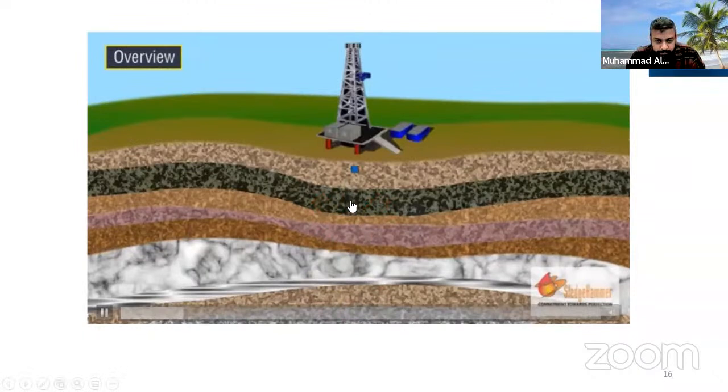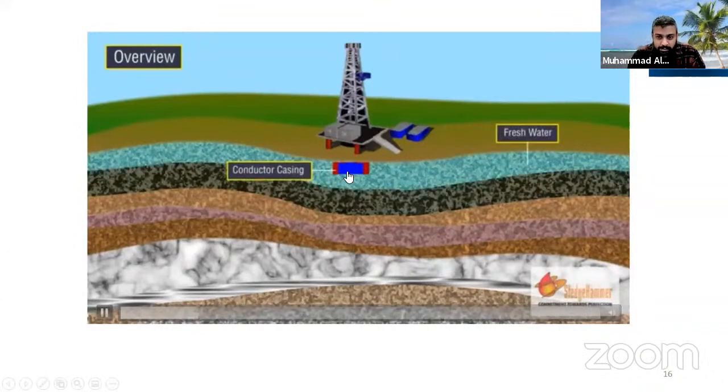Here you can see what we do. We first deal with the cave-in. See, this is the cave-in. Cave-in means that there are rocks that fall down inside. So when you drill and rock is falling down, then what is the point of it? So we have to save this. We don't want this caving-in issue. So what we do, we put the conductor. Once we put this kind of a pipe, the formation nearby cannot fall inside the hole and fill the hole, and we do it again. So that's why we put this conductor pipe here.